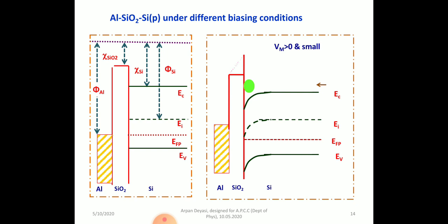Now, what will happen to the insulator band diagram? Please think. I am showing that the insulator band is now tilted towards the metal side and it will rise up at the oxide semiconductor interface. The question is why? Since you are sending more and more electrons to the oxide semiconductor interface, you have to prevent those electrons from surmounting the barrier and then going to the metal side.